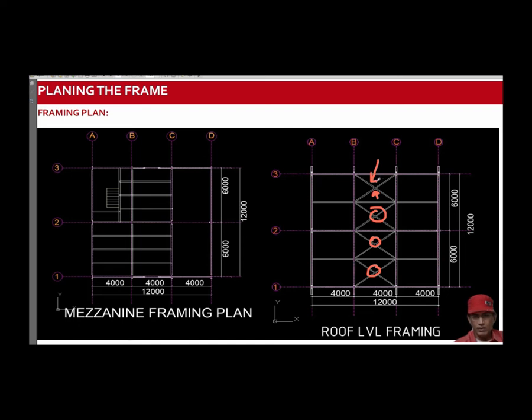Now, since in the response spectrum method signs are lost, it is difficult to perform dynamic analysis with the response spectrum method with tension only members.